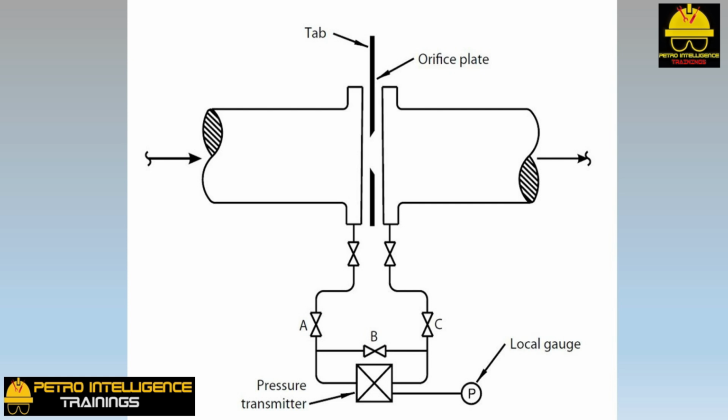If the flow transmitter is located below the orifice flanges, you will have to wait until the impulse lines refill with liquid. Open valve B and close valves A and C. Now wait until the flowmeter indication stops changing. It ought to go back to 0 if the lines are refilled.